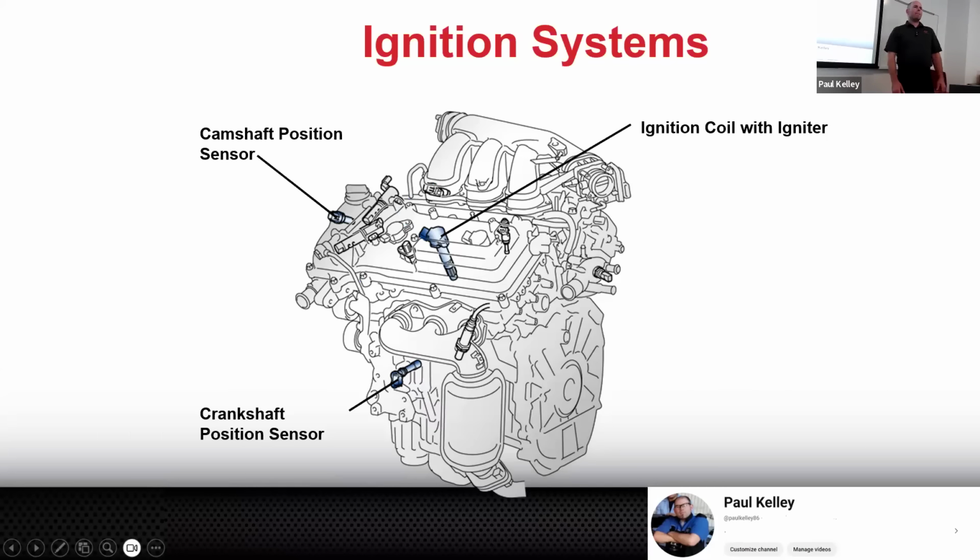Sometimes I'll shortcut that. Let's just say we move the spark plug from 3 to 1, we move the coil from 3 to 1 and move the spark plug from 3 to 5, but then we start it up and it still misfires on cylinder number 3. Does it need a new coil or a new spark plug? Neither. It really needs to be figured out. That's right. And so typically that's where the DIY people run out of gas.